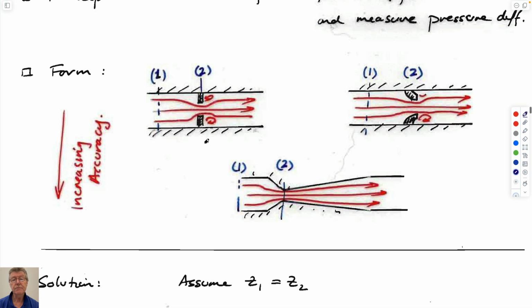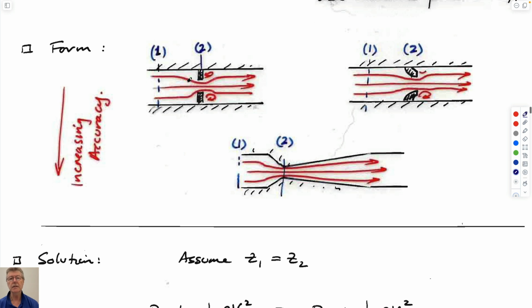So these Venturi tubes come in different varieties. This one is better than this one. It could be just a plate with an orifice in it. It could be an angled orifice plate, or it could just be a contraction in the pipe. The smoother the change, the less chance that you have all these vortices developing, as the question was last time. Why do these vortices develop?